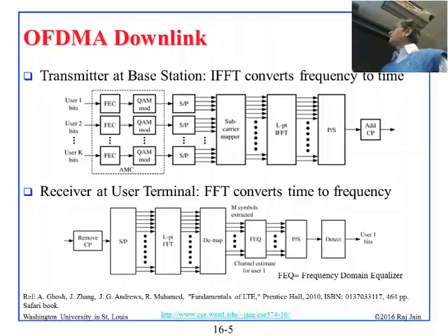So they are mapped here and they are demapped here. That map is transmitted in the frame beforehand, so you know which are your carriers. Then you use it. If your carriers change, this map will change automatically, and there is no extra work to be done anywhere. All of this is mathematics: IFFT, FFT, matrix multiplication. Whether you are doing matrix multiplication with 1024 non-zero numbers or with some zero numbers doesn't make much difference.